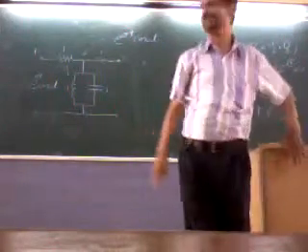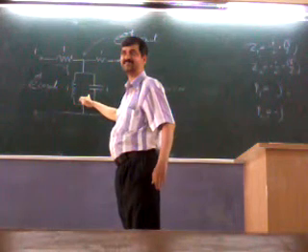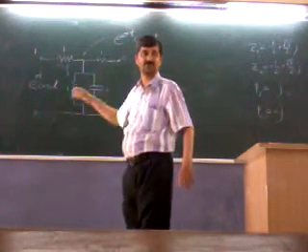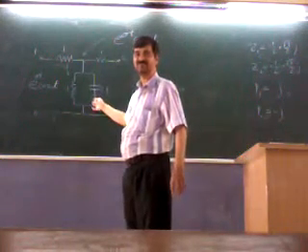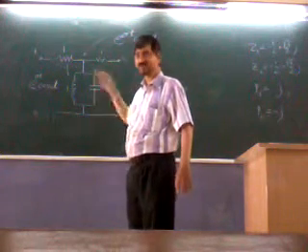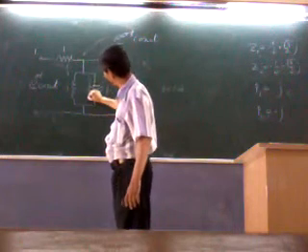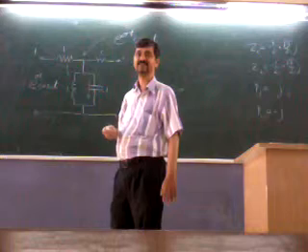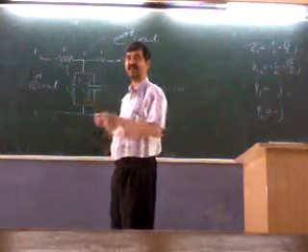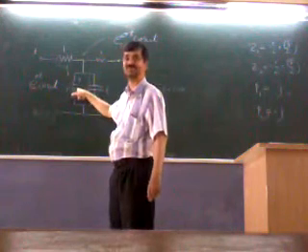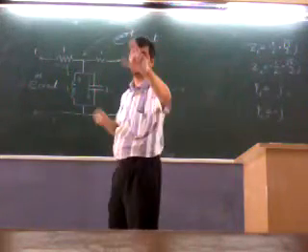When we apply that, what will be the current to this? No, why 0? We applied this, so it's derivative. We will get current here. But what we want is total current to be equal to 0. So if some current flows in this direction, what must happen? A reverse current must flow through this direction, right? And what is this voltage then? Its derivative, because L di by dt is 1, and that must be the same. So we can find it very easily.